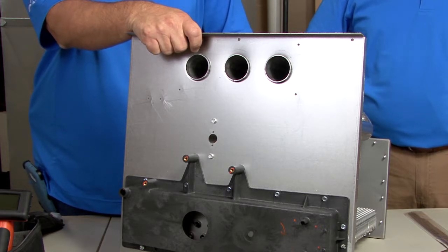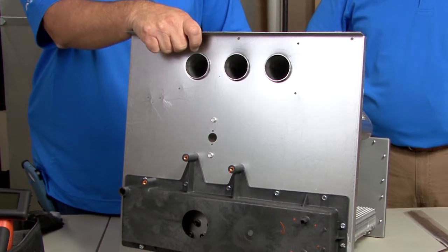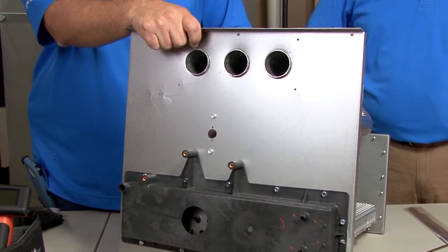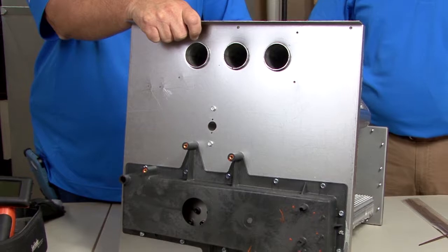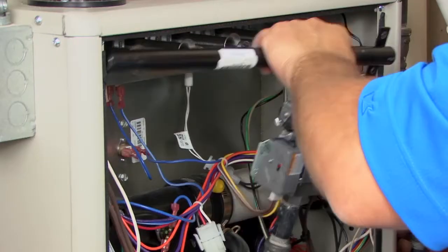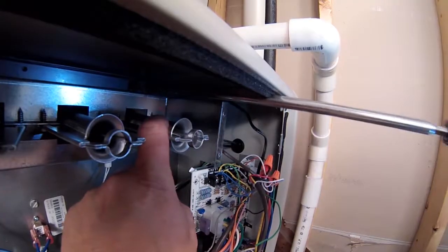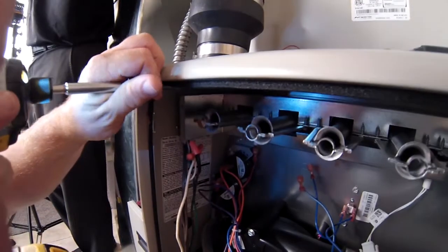In order to do this test, the only thing that's going to be running in the furnace is the main air blower. You're not going to have the inducer running. You're not going to have the burners on or anything like that. And it's also going to be my recommendation, even though it sounds like the more painstaking way to do it, when you do it on the furnace, to actually remove the burner assembly, because having the burner assembly out of the way is going to make this test so much easier to perform.